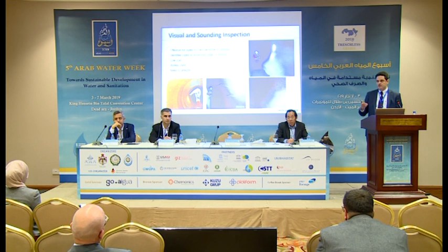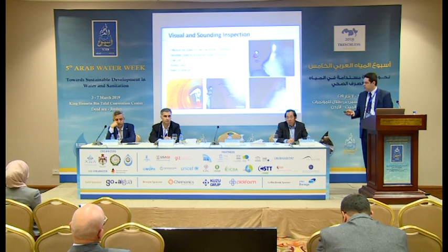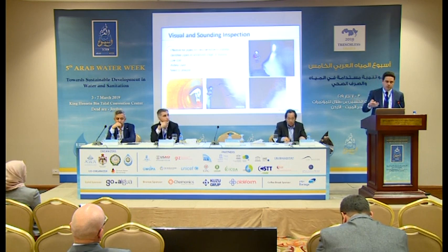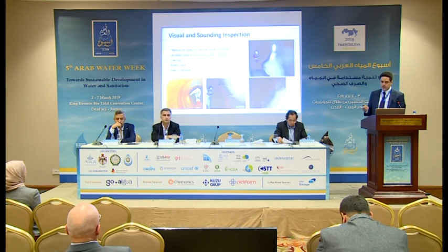Most utilities have some program to shut down their system on a periodic basis to allow such inspections to occur proactively. So what you are looking for is, by using trained inspectors, not just some average technician that looks at any crack, but a trained technician who knows the degradation process of that particular pipe, sounds and evaluates the observations to identify hollow sounding areas, longitudinal cracks, and what they mean in that particular situation.